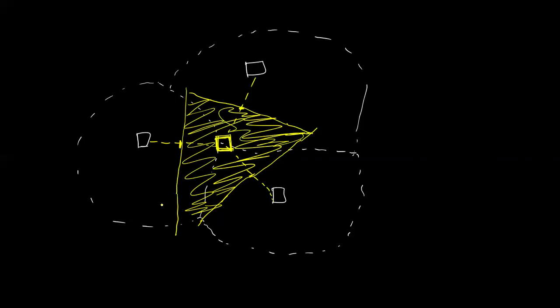So it is a thumb rule which is typically followed, and the remaining area goes to the existing substations. So that much yellow highlighted load present in that area is going to the newly constructed substation. So using the perpendicular bisector rule, we can simply follow that. And once again, where to put the substation? Once we have the area defined like that, we can now place the substation here, wherever. That is again an optimization problem.